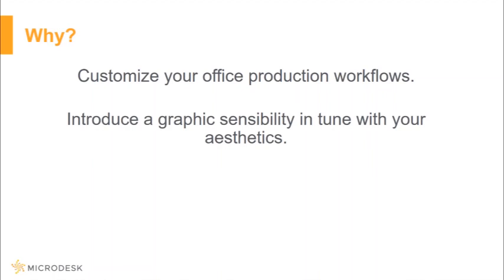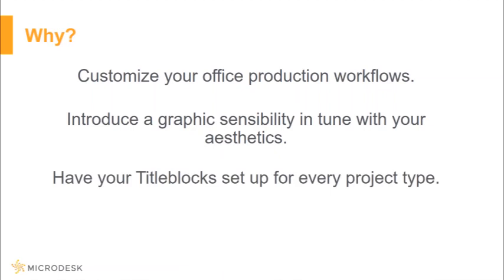You want to introduce a graphic sensibility. This is something that you can definitely do with your view template so that the aesthetics of how you want your drawings to look actually bump out and look a certain way for your office. This is something that I hear a lot, that Revit drawings look the same, and I think this is something that can definitely be tuned and catered to how you want your drawings to look via view templates.